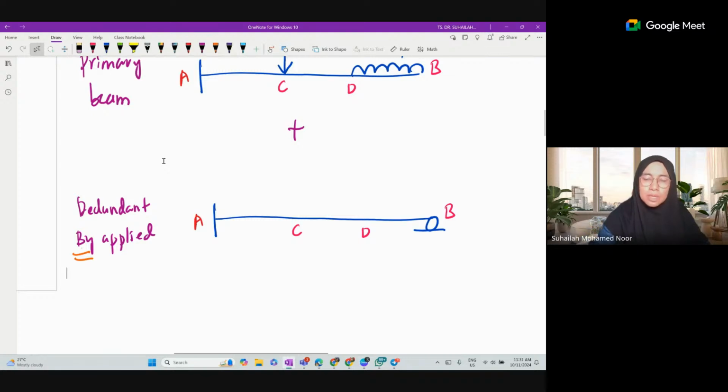Okay, so it is a cantilever beam subjected to a unit value of BY. So the BY that we remove from the system, we put into the redundant beam, and since BY is the unknown, we cannot analyze BY.